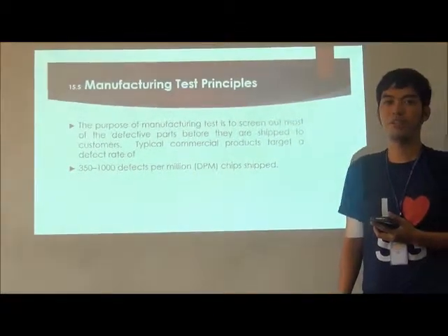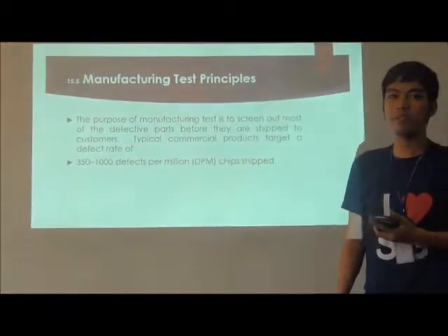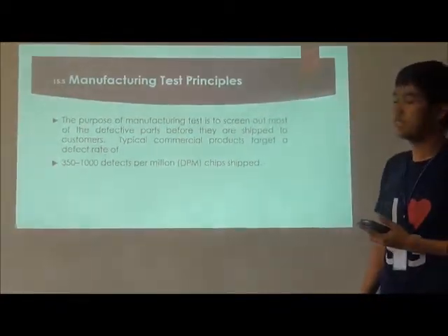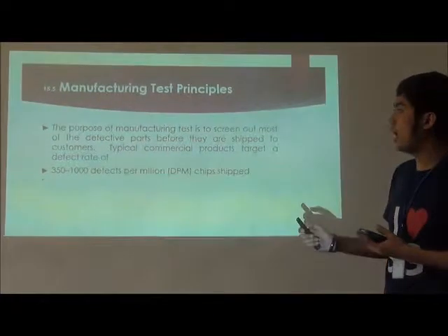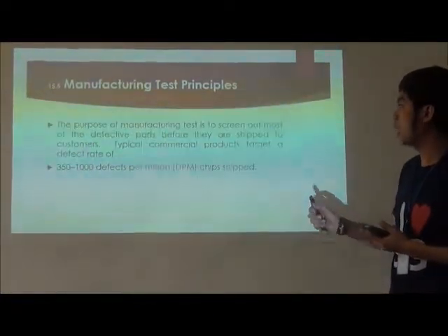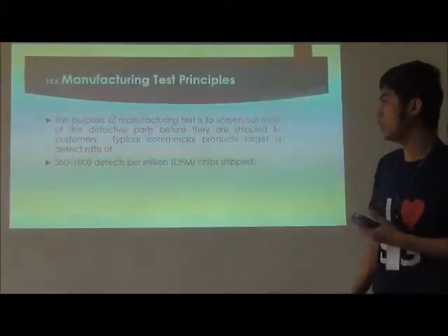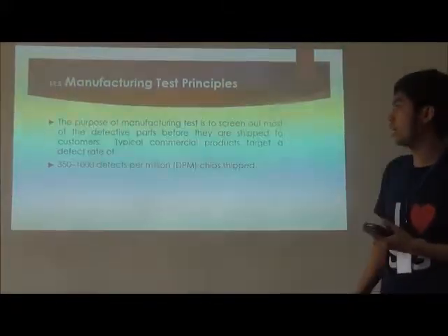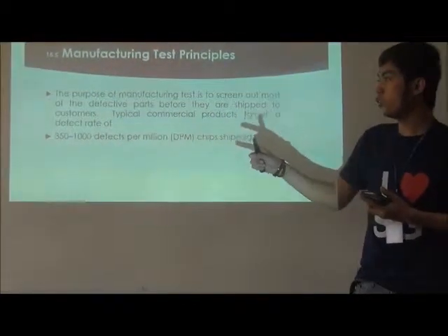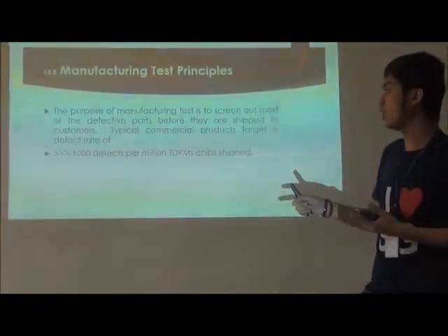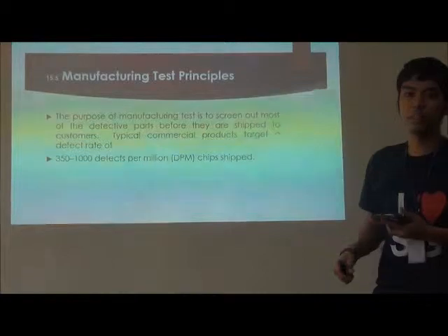Sure. Good afternoon. So, 15.5, manufacturing test principles. The purpose of the manufacturing test is to screen out most of the defective parts before they are shipped to customers. Typical commercial products target a rate of 3 to 1,000 defects per million, or DPM, chips shipped.